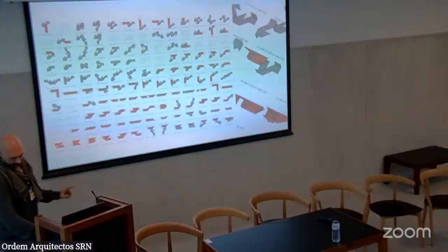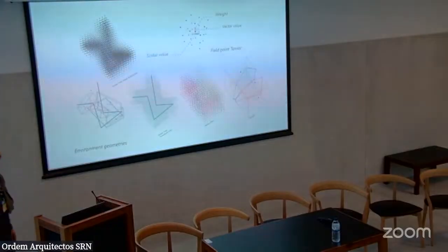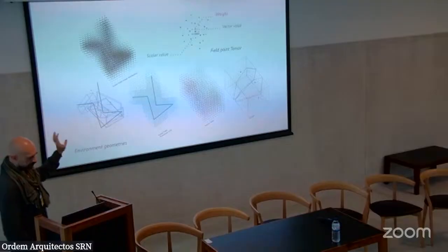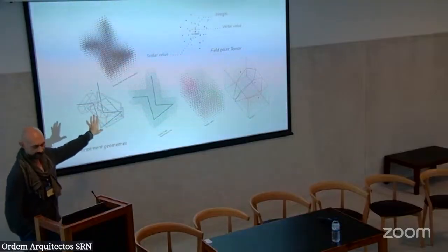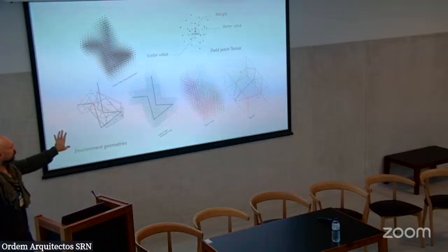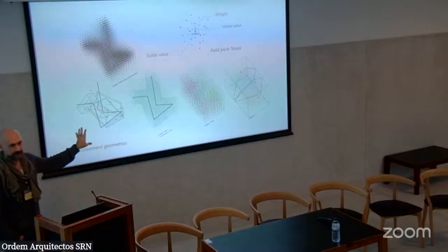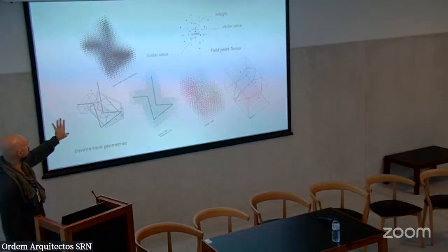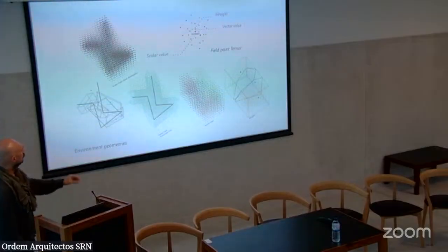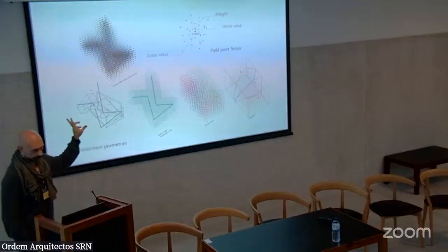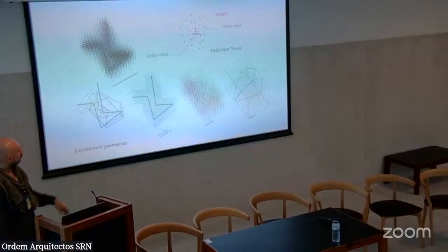Then you can set up the exogenous information, that is environmental data, which are basically encoded into an object that is named field inside assembler. What a field is in assembler terms is a 3D voxelized space. So you can assign to each center of the cells, each voxel point, three kinds of values: a scalar value, a vector value, and a weight, an integer weight.